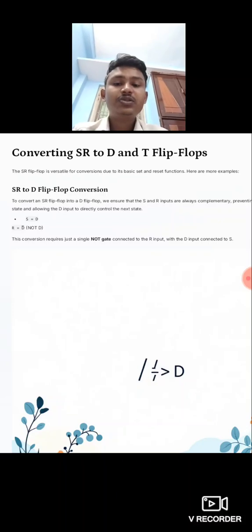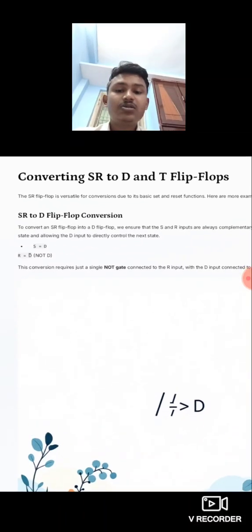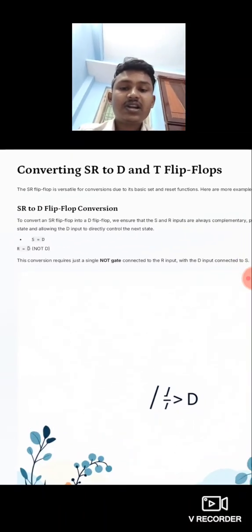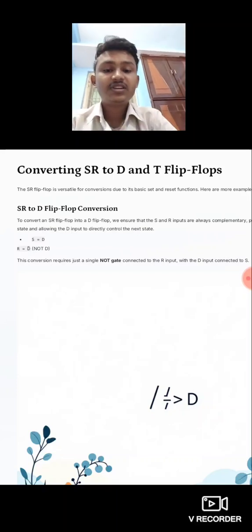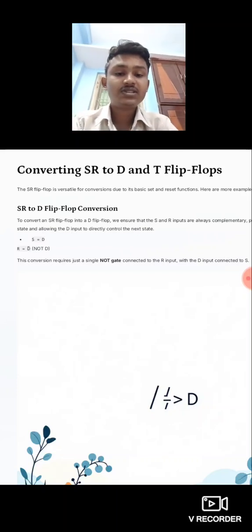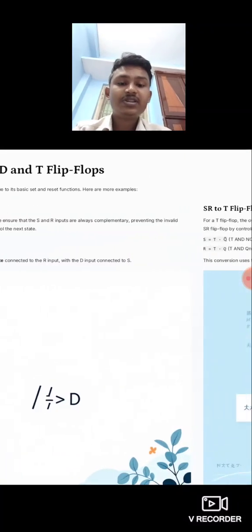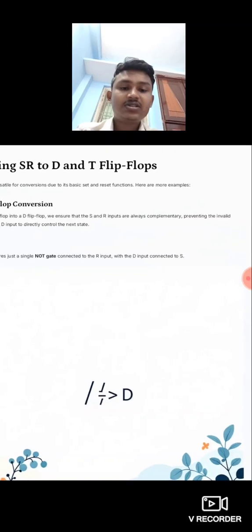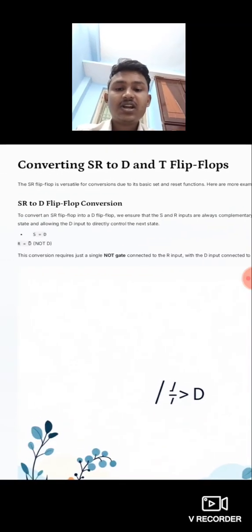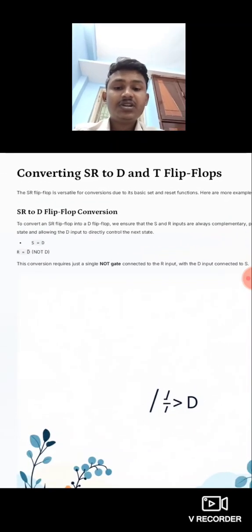SR flip-flop to D flip-flop conversion. To convert an SR flip-flop into a D flip-flop, we ensure that the S and R inputs are always complementary, preventing the invalid state and allowing the D input to directly control the next state.